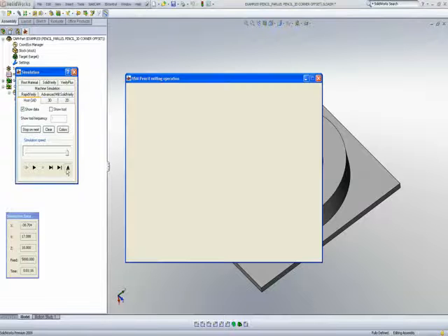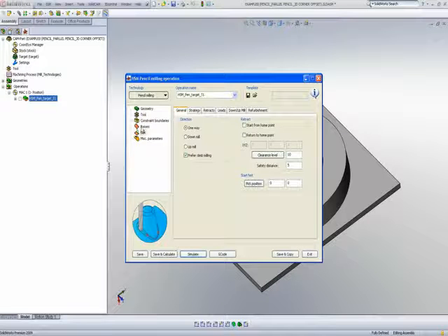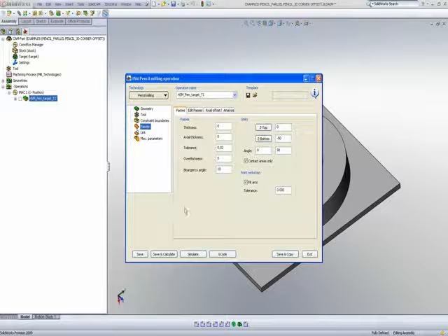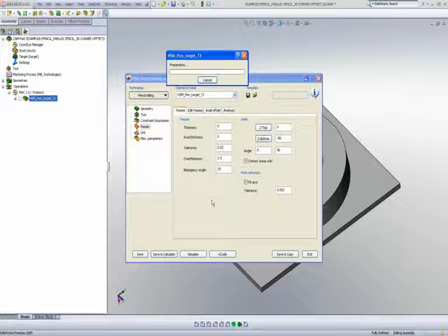So what we can do to compensate for that is simply go into our passes area, and we have this option called overthickness. What overthickness does is takes the tool, and if I were to say add 1.5 millimeters on the side of the tool, all of a sudden the tool will actually be able to pick up those passes, and it'll work in those areas also. Now let's just do save and calculate, and then we'll do the simulation again.